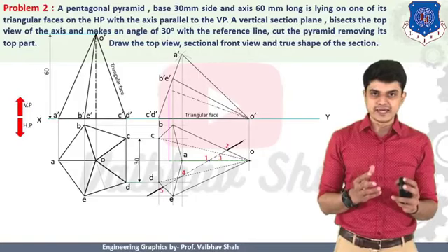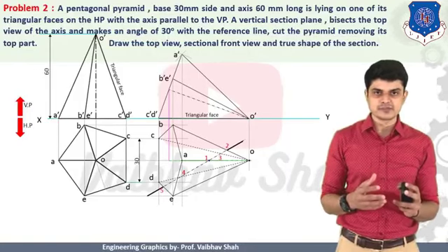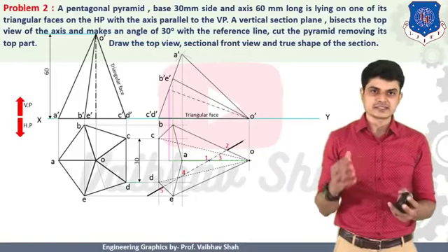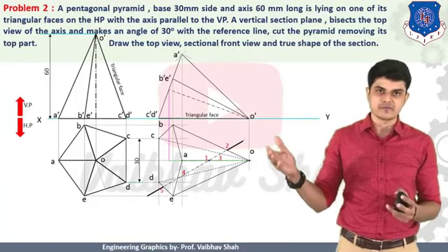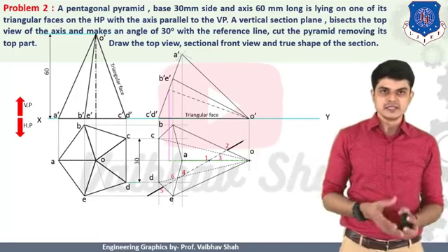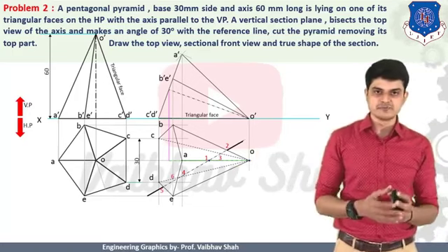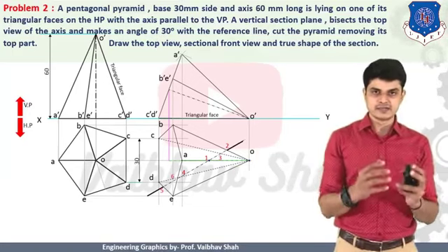After getting point 5, we should now return back because the point D is reached. So let us go back. So we should find out the point D. So we will be having this line OD, which is the back of the object. So we will be having point number 6. So these are the total complete number of points in which your cutting plane line is cutting your object.